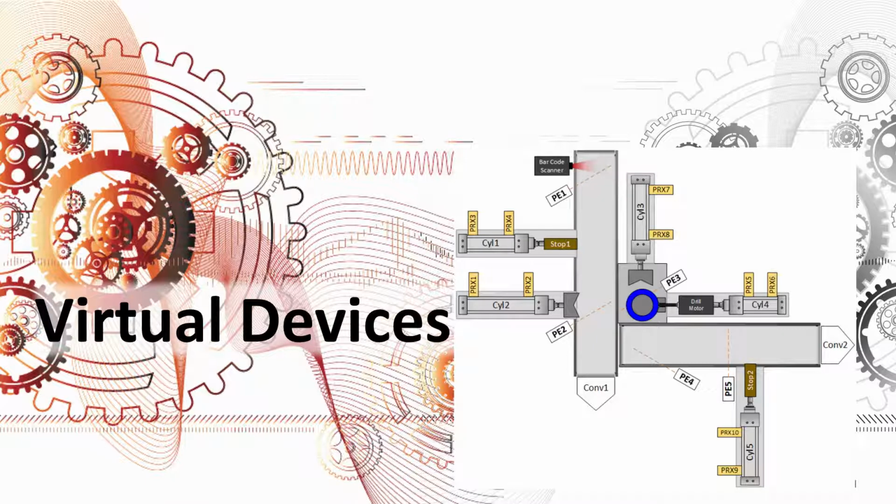To increase the size of our virtual process or machine and reduce the complexity, we write code that represents virtual devices. In other words, in the first one we're going to do for a pneumatic cylinder, when you energize the solenoid, that solenoid valve, the electromagnetic force of the solenoid, pulls or shifts the spool to shift where the pressure is applied to the cylinder.